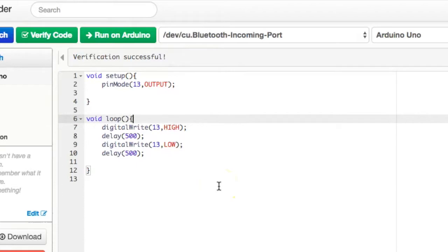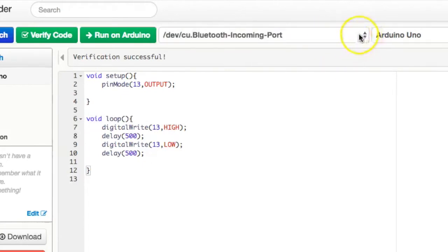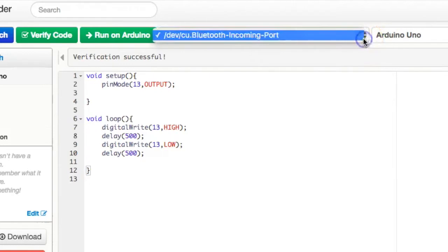Now, your students will connect their Arduino Uno to one of the USB ports in their Chromebooks, and they will choose one of the ports. When your students click on this down arrow, they will be able to choose from 2 different ports. They may test out both ports.